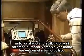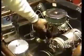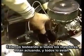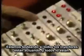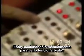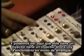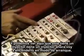Let's hook up the distributor and just rotate the engine because I want to see what it looks like with the same pulse. Just testing to see if all the injectors are firing, and they are firing. I'm actually turning it manually to watch it fire. Okay, and you can see right here, this one has an injector. That has an injector. That has an injector. Now I'm going to turn it the way the car normally runs.